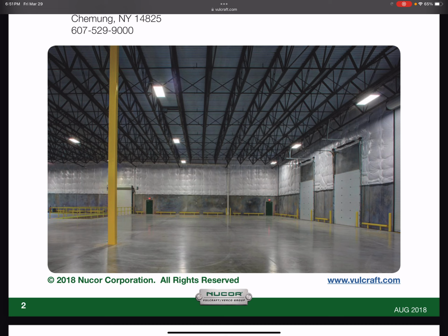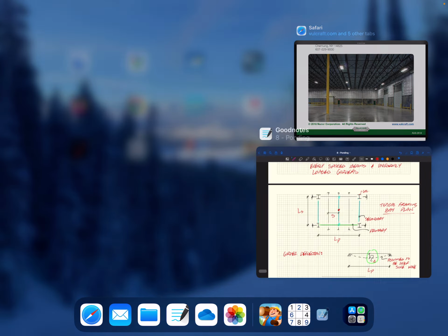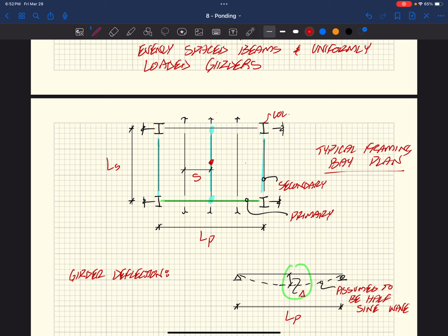And in some cases, if you have a thick enough metal deck, you might be able to span 10 or 12 feet. And so maybe you get rid of the girders in that drawing. Now all of a sudden the decking spans far enough. Well, I guess we get rid of the secondary members and the deck just spans between girders. And so that might be the case.